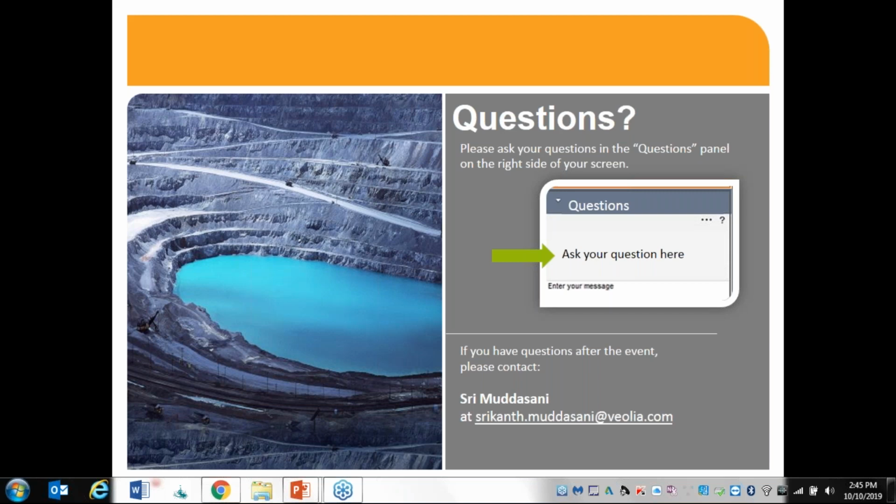You reduce the pH down to 6.5, and at that pH, the solubility of aluminum hydroxide is very low. You'll be able to precipitate all the aluminum hydroxide back from the ettringite solids. That's a very good question.